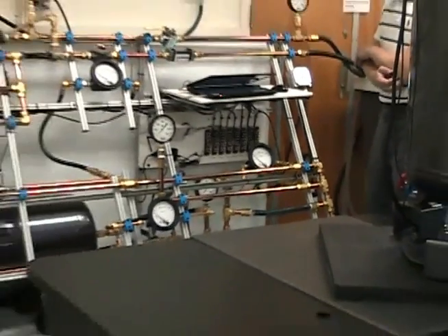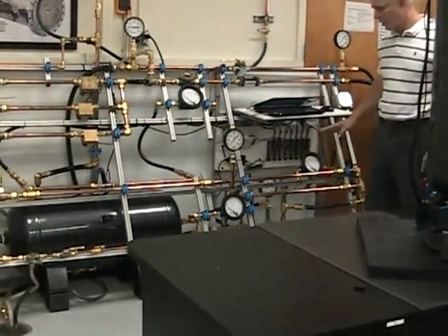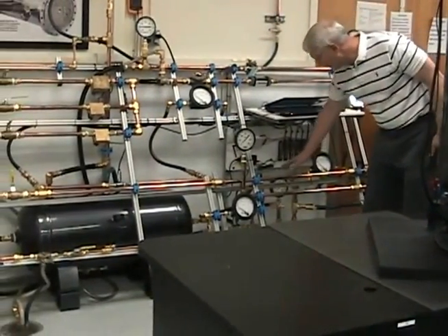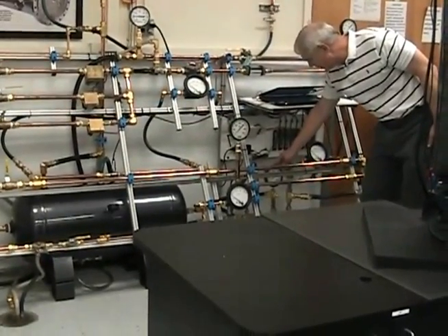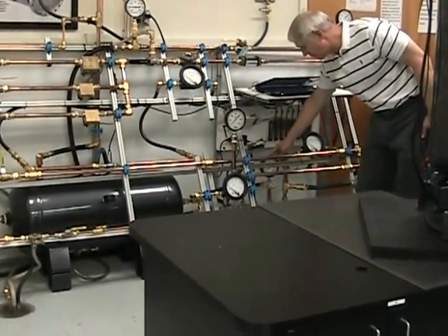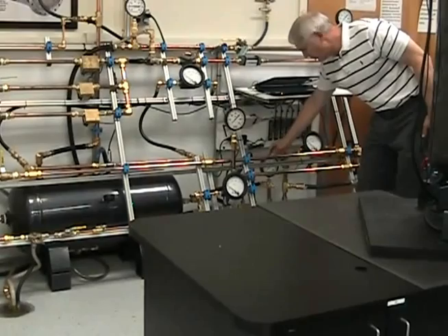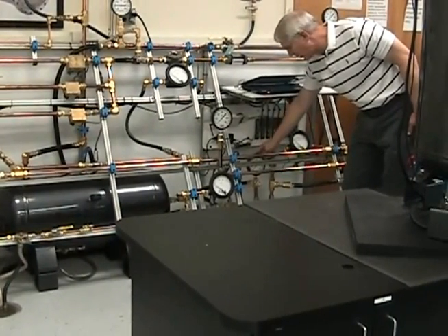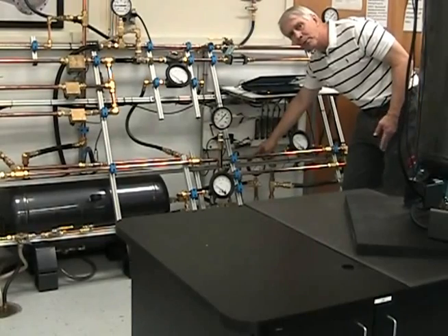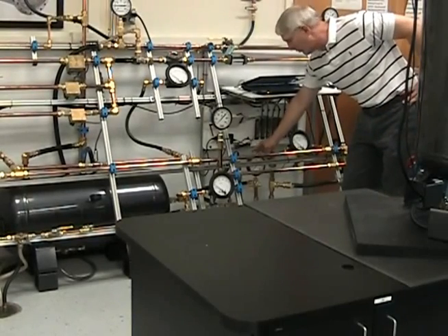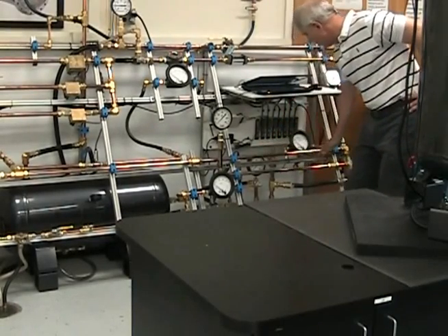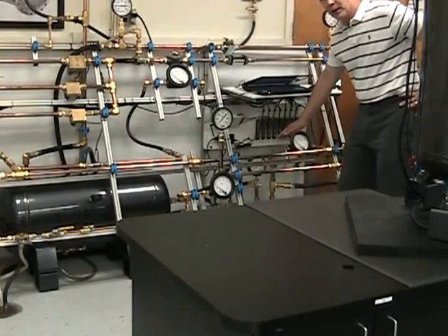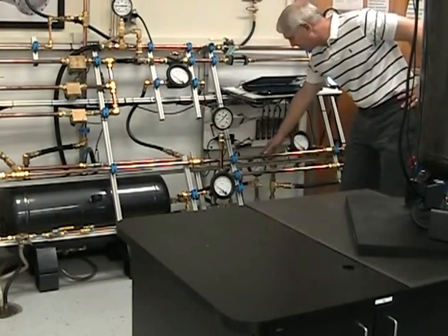We also have a few other pressure gauges located around, so you want to look at those. Right here is a pressure gauge, which measures the gauge pressure coming out of the pump. So this is the pressure directly out of the pump. With the valve all the way open, it should be somewhere between 25 and 40 psi. If we close the valve down, we can get it to almost 300 psi.